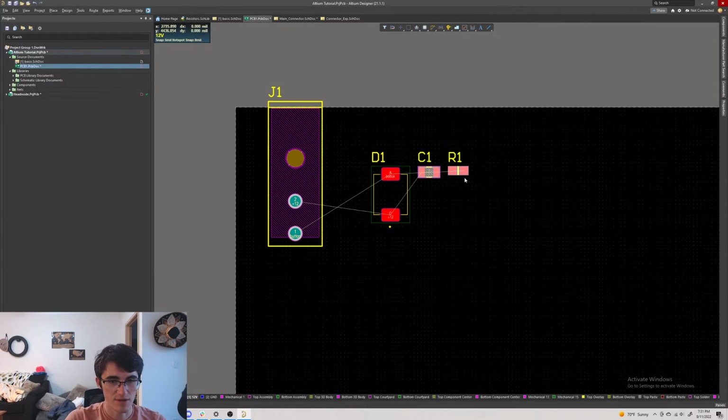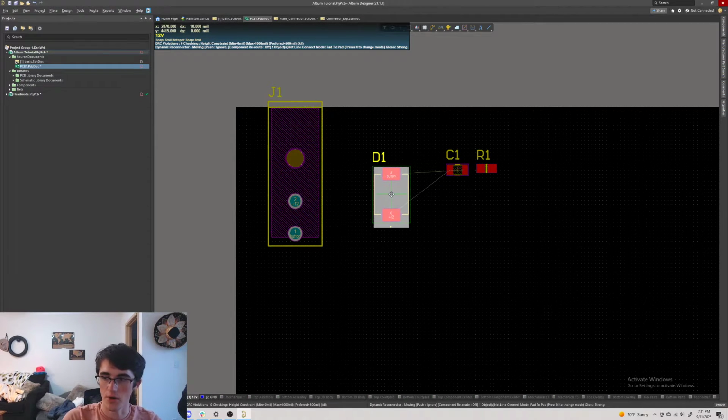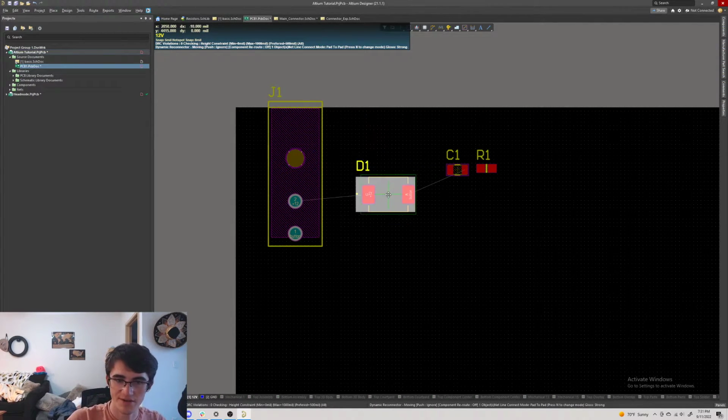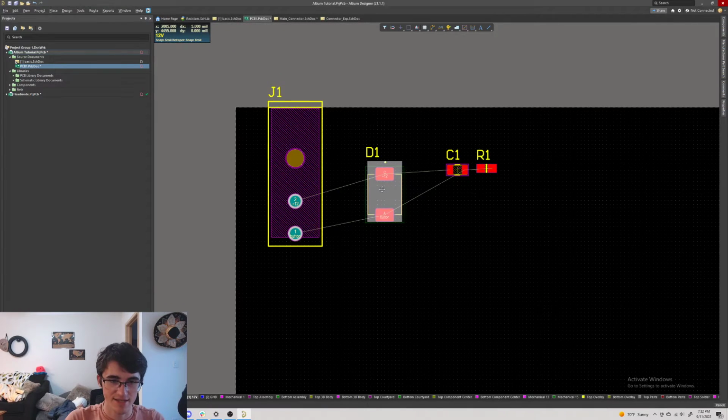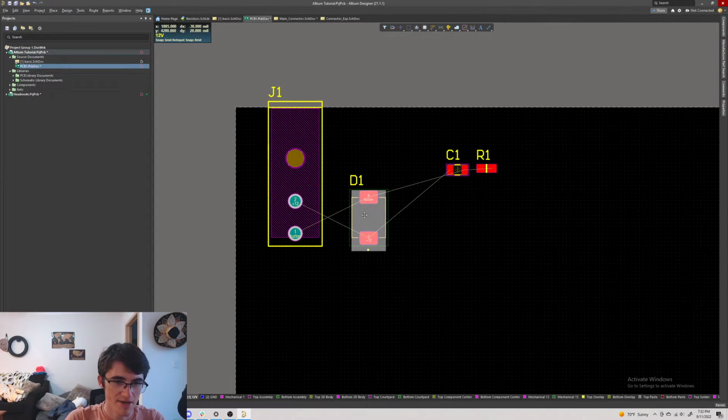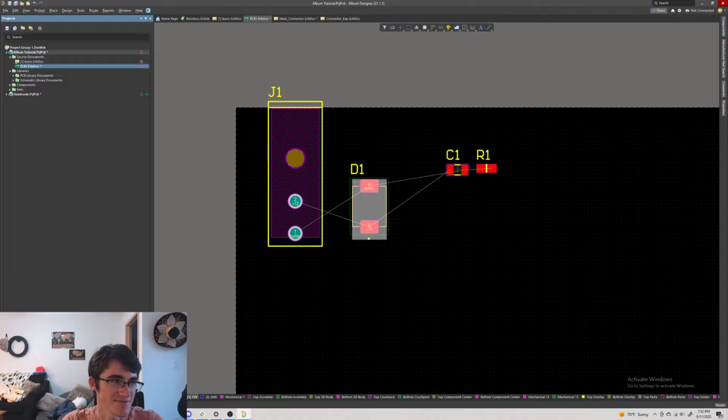So some other stuff you can do to change the parts is you can select the part and then click and hold it. And if you press spacebar, you actually can rotate it. And so that's so you can get easier traces. So you can see here, oh man, like it wants 12 volts here, and then it wants this ground or this button trace, I guess, since we shorted them together.